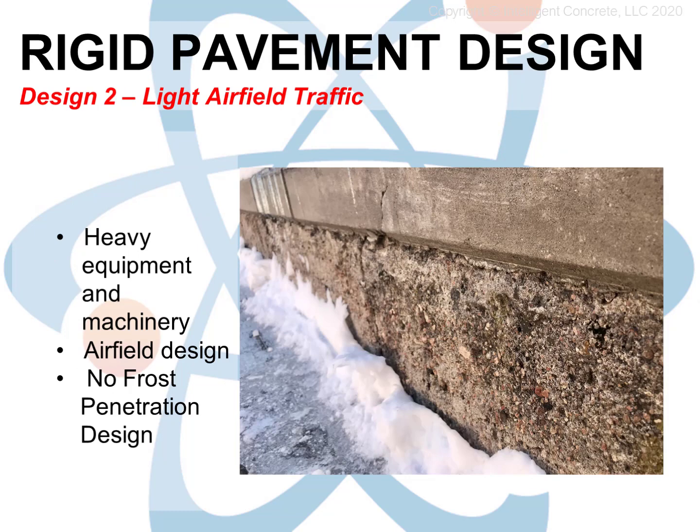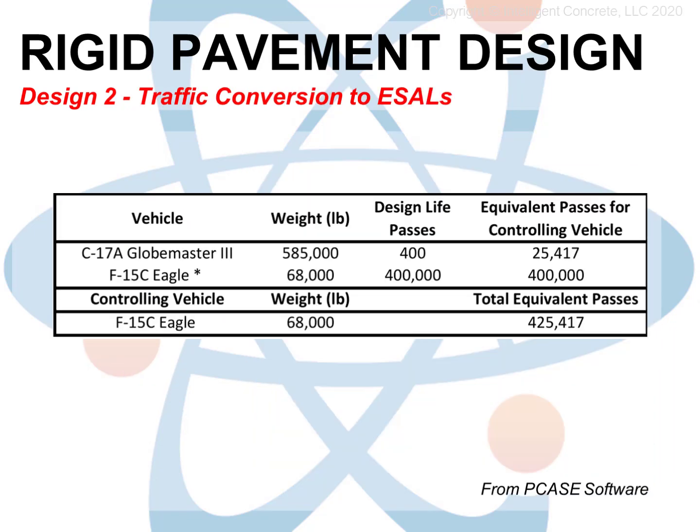For the second design, we'll use a standard load for light Air Force traffic provided by the P-Case software. It is not designed for frost protection. Bear in mind that software such as P-Case gives the operator an option of selecting standard, well-researched traffic patterns, or the user can input custom traffic patterns. For this class, we're just going to pick standard patterns. The standard light traffic pattern we've selected uses C-17s and F-15s. We could also pick standard patterns for other cargo planes and fighter mixes, bombers, tankers, and so on. It's definitely not a one-size-fits-all. There's a lot of room for customizing even within the standard patterns.